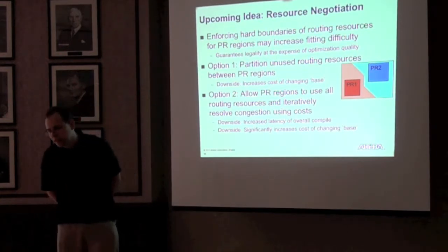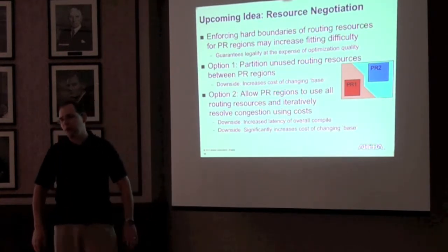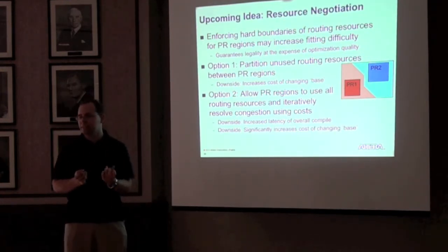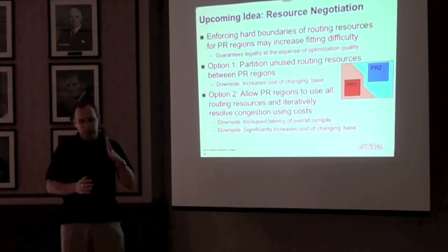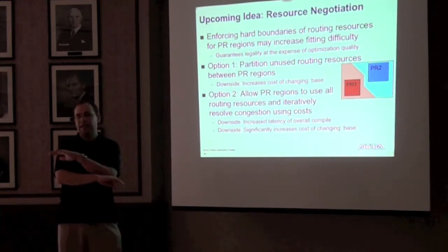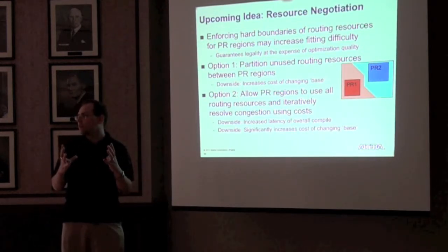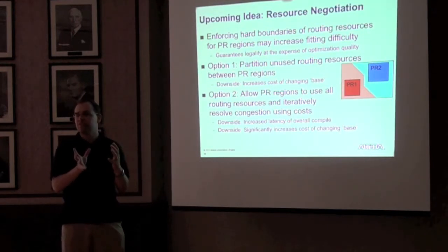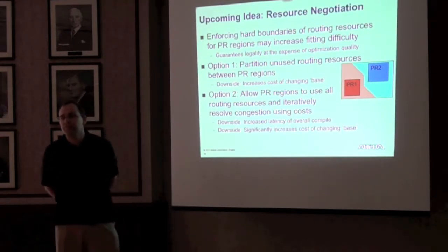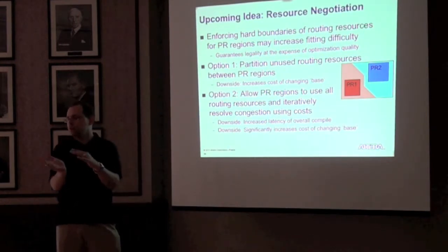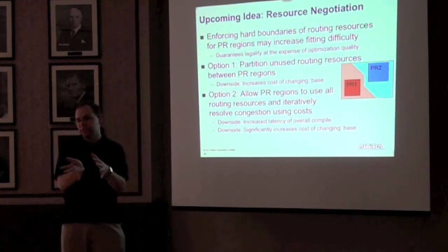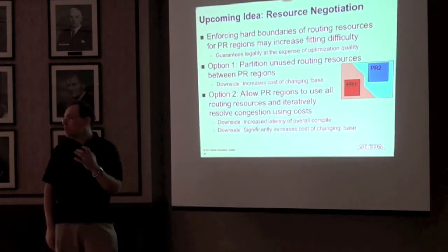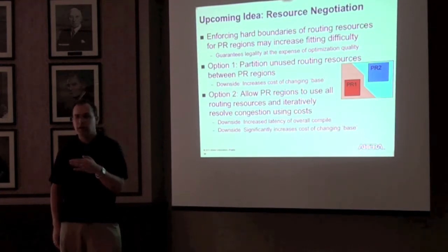That's a great question. So can PR be used to lower power by putting it into a low power state? You can actually do better than that. One of the personas that is implicitly created is sort of the empty persona, which is just those anchor LUTs and nothing else. So if you really don't want to use that block functionality, you can program in through a PR sequence that empty bit stream, and then you have no LABs. Of course, if you wanted a lower power implementation of the same function but slower, that's another option. So you can in fact implement the exact same functionality, but just with a different power performance trade-off.